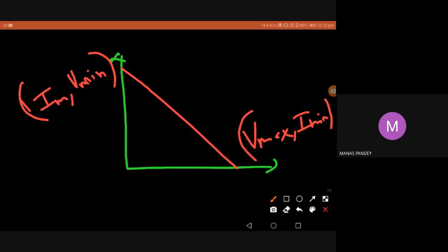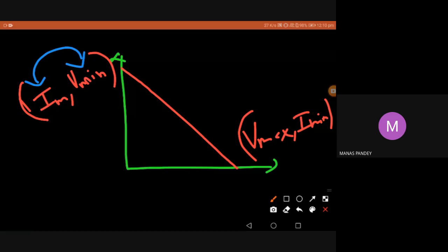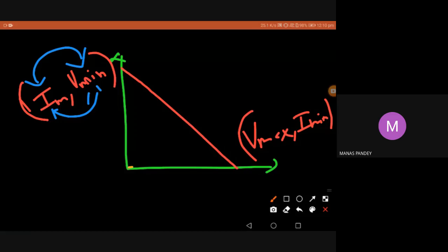Okay, this should be reversed. First you specify the x-axis, then you specify the y-axis. Okay, so fine. Then over this load line, you plot your device characteristics. Then you go to the intersection, and that is going to be your Q point. So say V star, the operating voltage, and the corresponding I star.